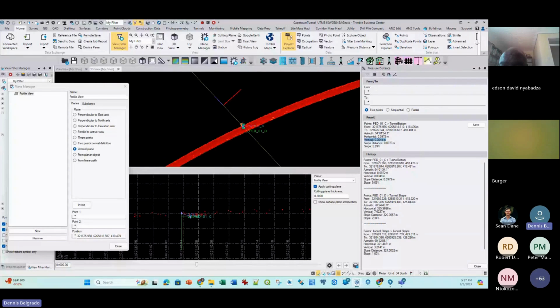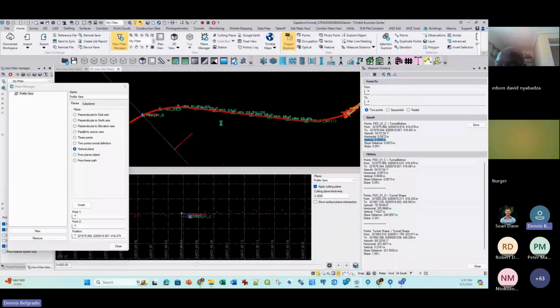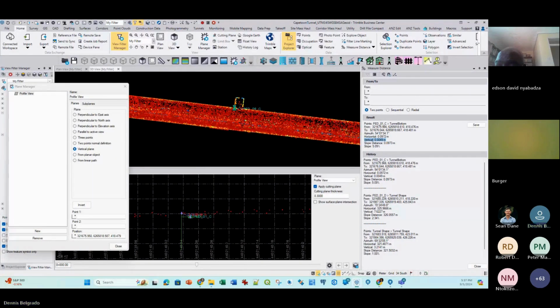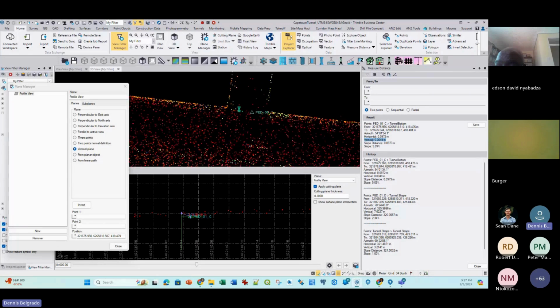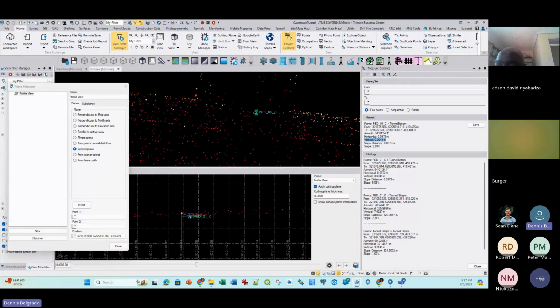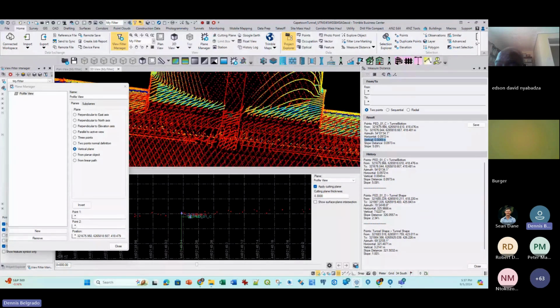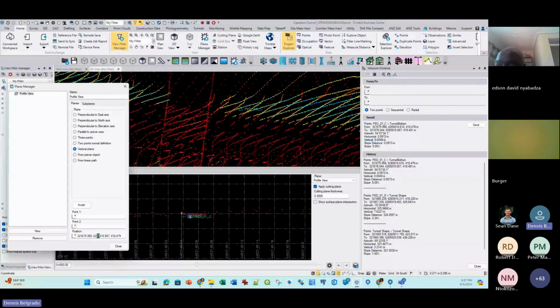So what I'll do is I'll take another example somewhere in the middle. Definitely around 2 kilometers in, there won't be GNSS signal, right? So by that time, the accuracy from the IMU or inertial system has already drifted. So I will go ahead and select that again.